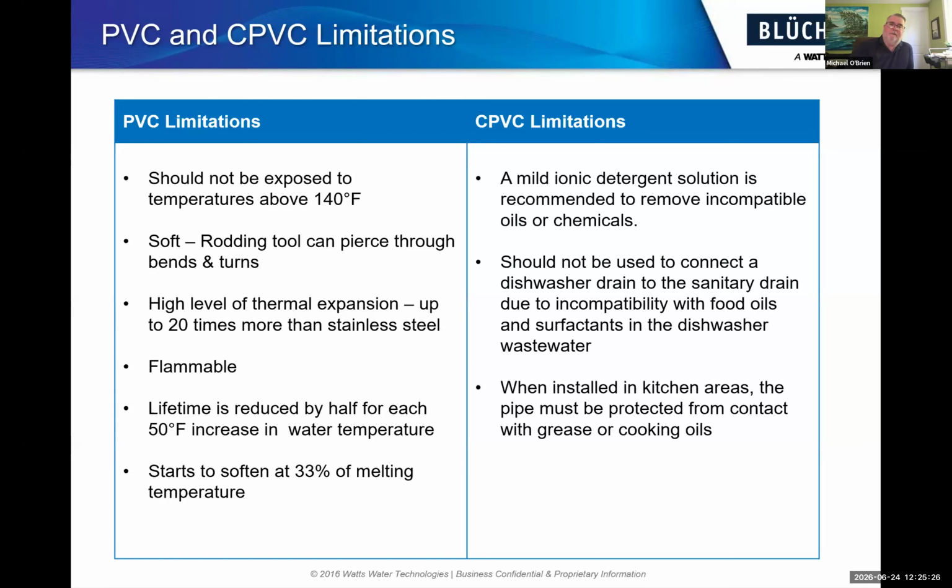But then once it returns back to temperature, it won't find its original dimension, and therefore you have a spot for water to bypass the drain and get down underneath the floor, where it may or may not cause any problems, but likely it is. Likely it will be a harborage spot for bacteria, and could be over time undermining the foundation of the building.